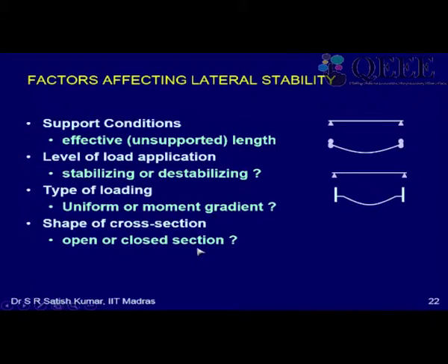And if the sections are closed, like in a circular tube or a rectangular tube, whatever, then there would be hardly any warping. And also note that a rectangular tube has two webs. Okay, it's like having two webs and two flanges. So the two webs will contribute significantly, even by the A R squared of their property, to IYY.